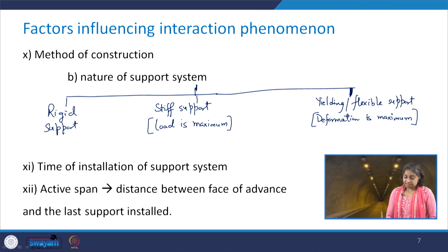Then the next factor is the time of installation of the support system. I have already mentioned to you that it should be done within stand-up time, and in case the stand-up time is very large, it is not necessary that you wait till the end of the stand-up time and install the support system just before that. The installation of the support system should be done as soon as possible after the excavation.